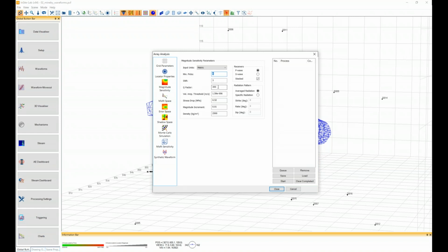And here, all we need to input is basically what's roughly the properties of our rock mass. That's given by the density and the Q factor, attenuation that we are expecting to have. Some parameters characterizing our tools, and what is the minimum number of peaks that we want to have for one event to be properly detected. I'm being quite conservative here, asking that it has to be detected by a minimum of 6 stations. So let's run it.